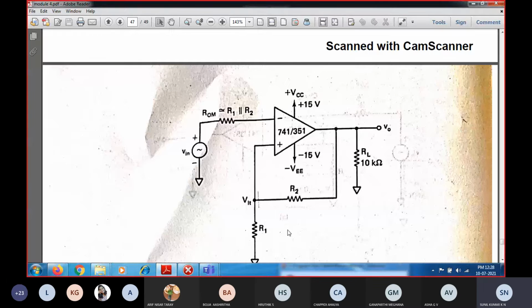So minus 7 volts is the reference voltage now, whereas previously it was plus 7 volts because of positive saturation. Now, whenever the inverting input exceeds the value of the non-inverting terminal, the output switches from positive to negative saturation.